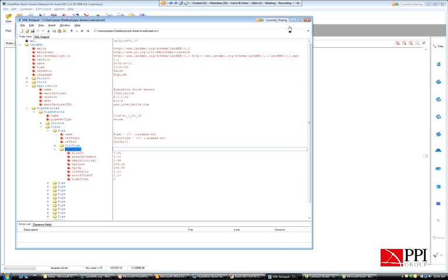You can also, just to be aware of your watershed tools that are available in the display and being able to extract those off of the surface, and then the ability to communicate not only with hydrology and hydraulic programs, but also bring them into your custom spreadsheets that are already built through Land XML, using XML Notepad and creating schemas within XML.